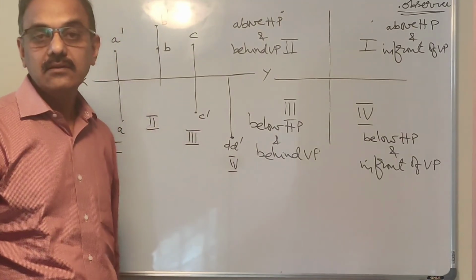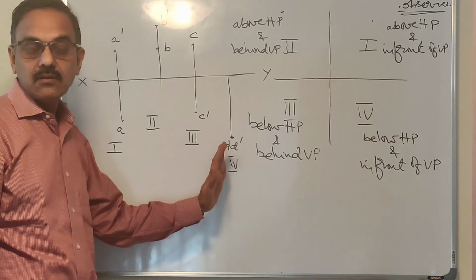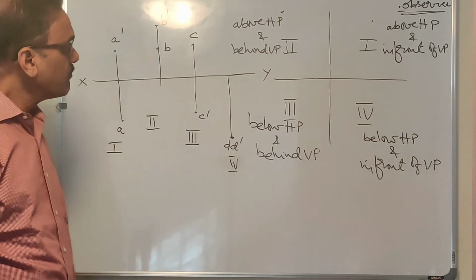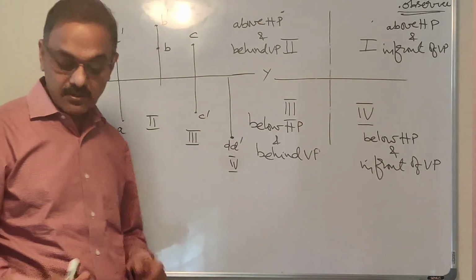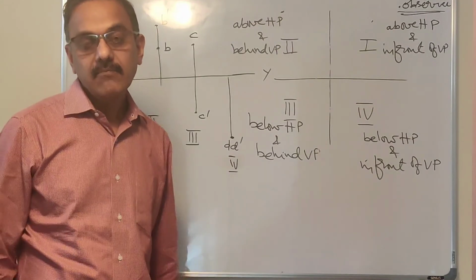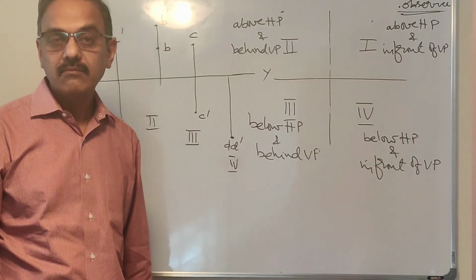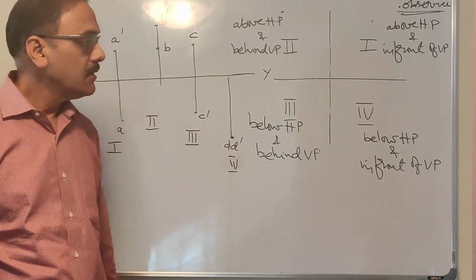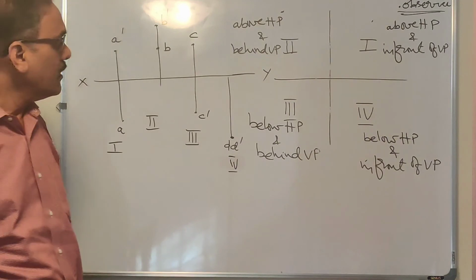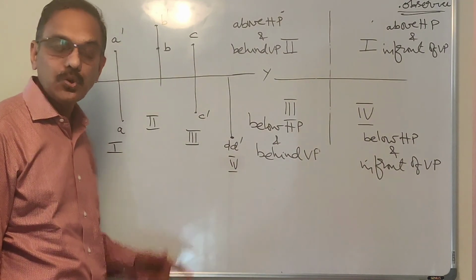That is another reason why the second and fourth projections are not followed. Okay, so this is a very important point, the reason why the second and fourth projection methods are not followed. It is not explained in the books. But this is very important for anybody who is practicing engineering drawing to know this.